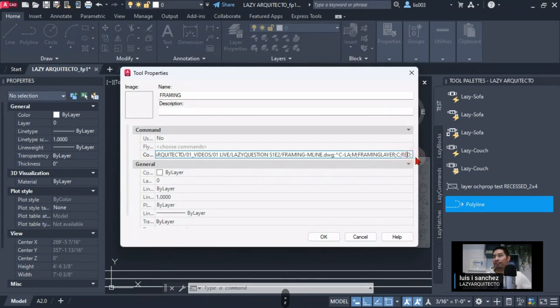So red, again, that's a simple color, but we need to accept all of these settings. Color, we need to accept layer, and so on. So we need a couple more enters in this case. I'm going to press enter two times. So that will give us the option to set a layer, set a color, and insert our multi-line styles.